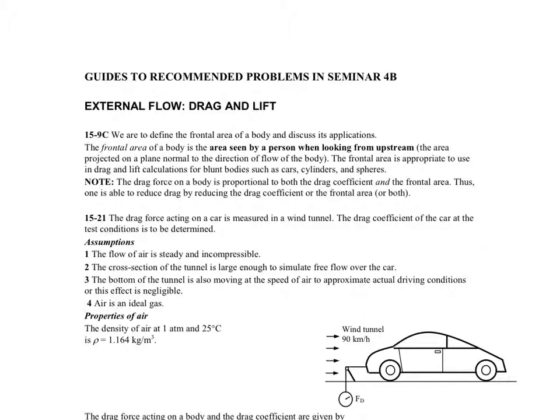The frontal area is appropriate for use in drag and lift coefficients for blunt, or sometimes they are called bluff bodies, such as cars, cylinders, and spheres. You can look at the example 15-21 just below to give you an idea what is meant by the frontal area.